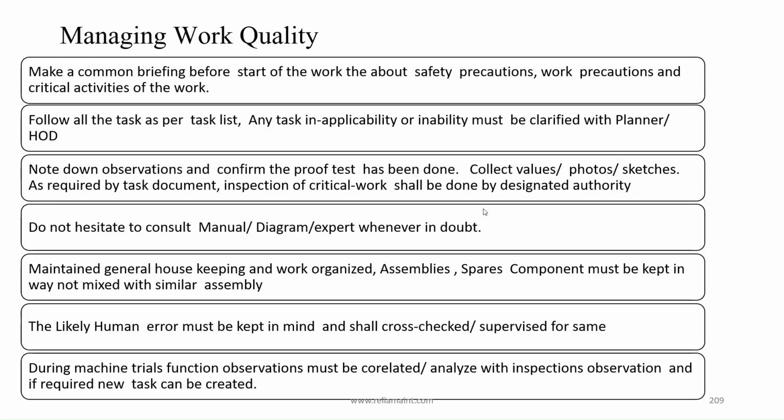Managing work quality. Make a common briefing before start of the work about safety precautions, work precautions, and critical activities of the work. Follow all the tasks as per task list. Any task inapplicability or inability must be clarified with planner/HOD. Note down observations and confirm the proof test has been done. Collect values/photos/sketches as required by task document. Inspection of critical work shall be done by designated authority.